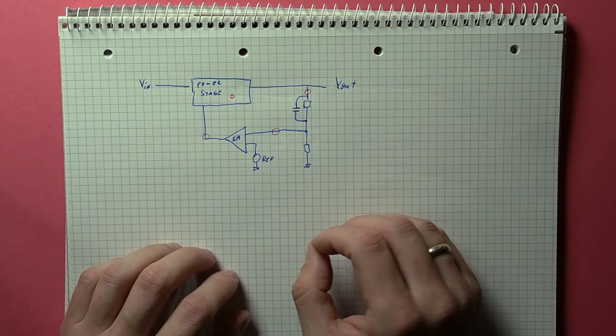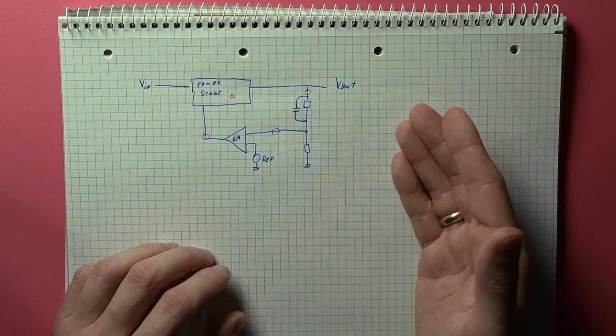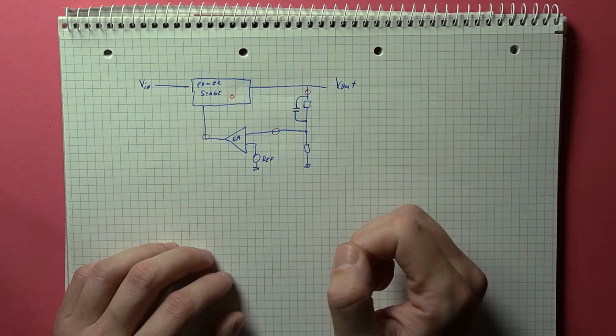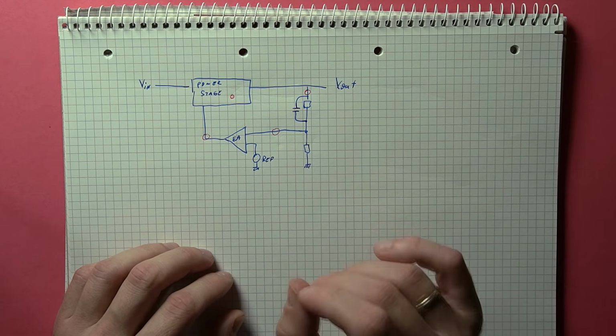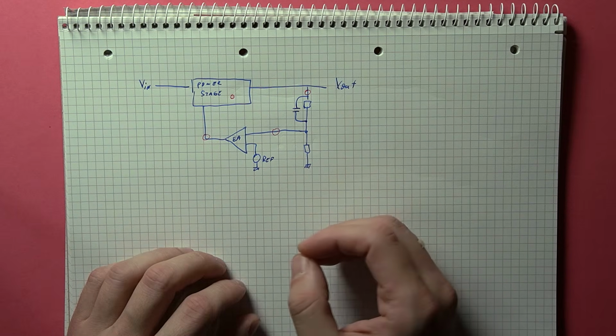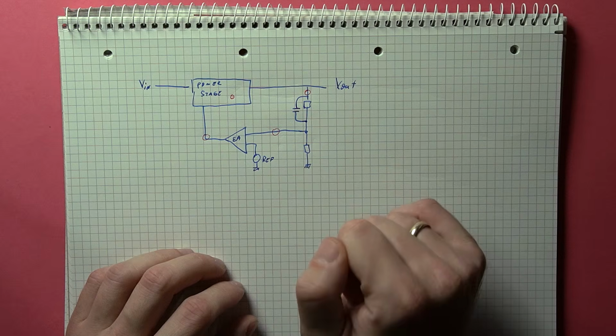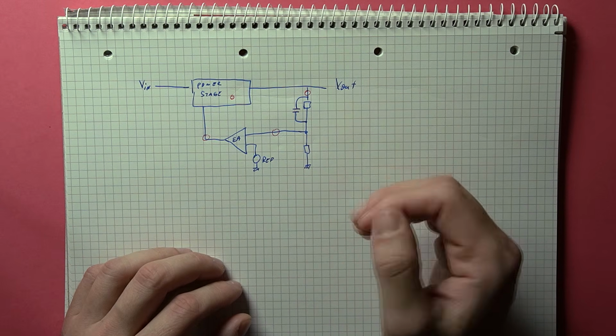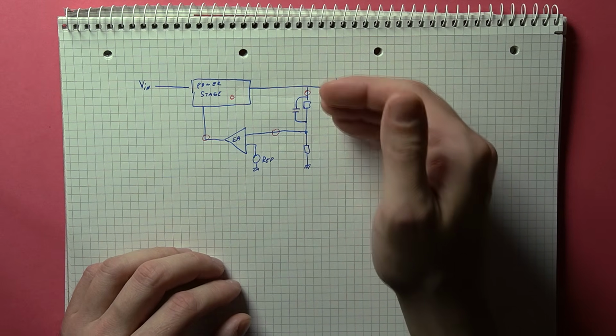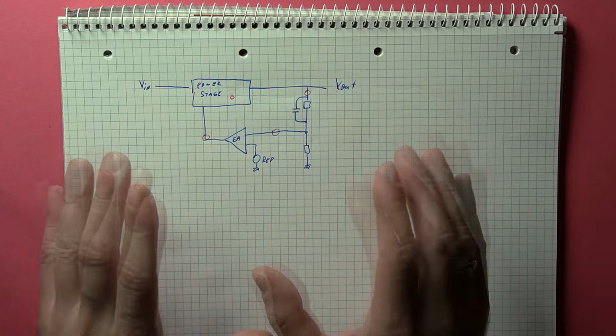Final thing to mention here is that if you have other components, like some capacitors around the feedback resistors, these are also part of the feedback network. So the signal injection point should not bypass these. With this sort of setup, the interruption needs to be between the output and the rest of the circuit to get a correct result.